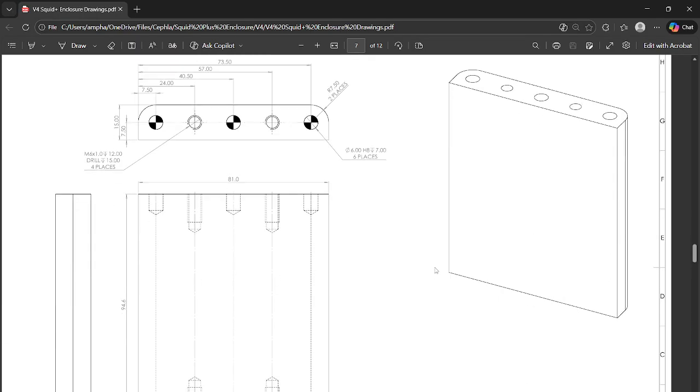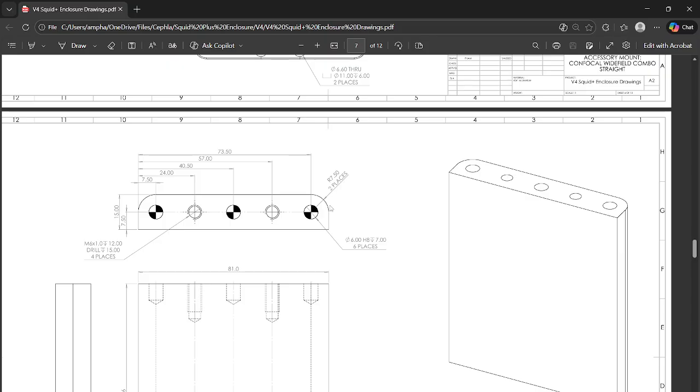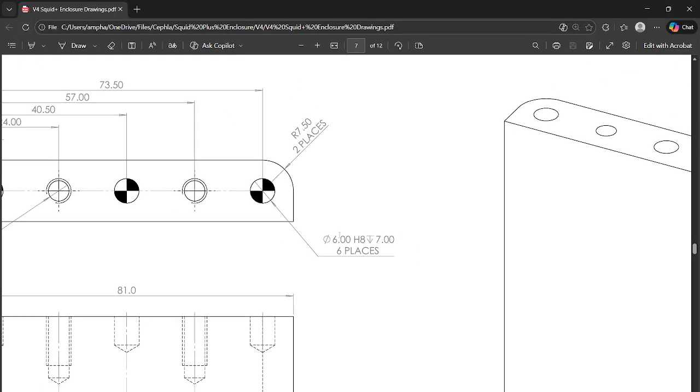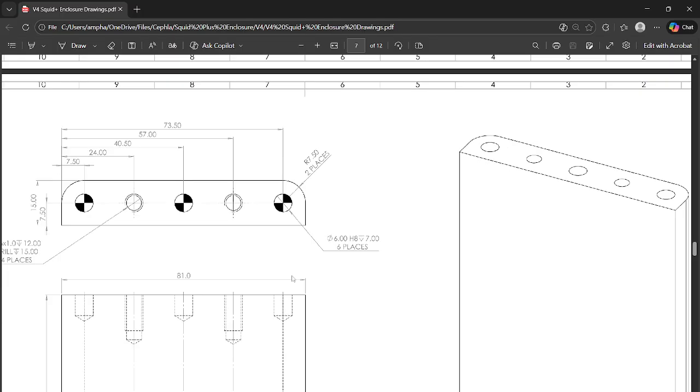If you're interested in this, you should take the GD&T course because that's kind of what they go over. But you can see here, I have holes for dowel pins and stuff like that. And I use the hole tool. I use a different software, SolidWorks. But when I click on this hole while creating my part drawing, it already gave me all this information. I think I only had to add the H8, but all of this was already there. So it's a lot of nice information for the machinist to know, and it speeds up the process when you create these drawings, right?